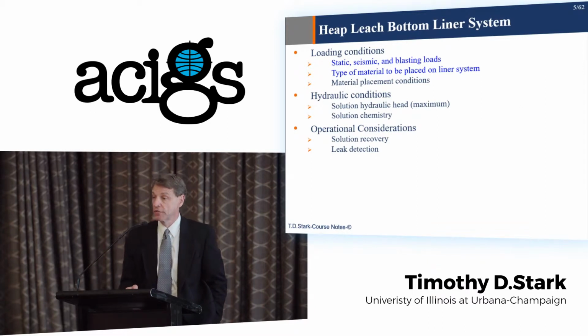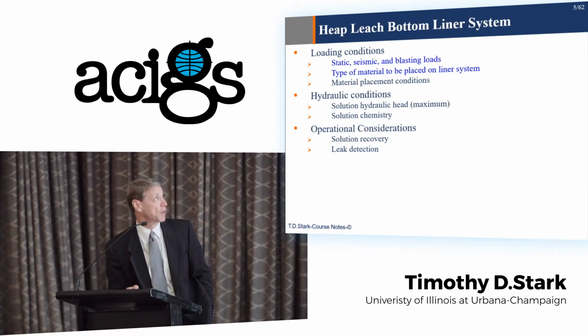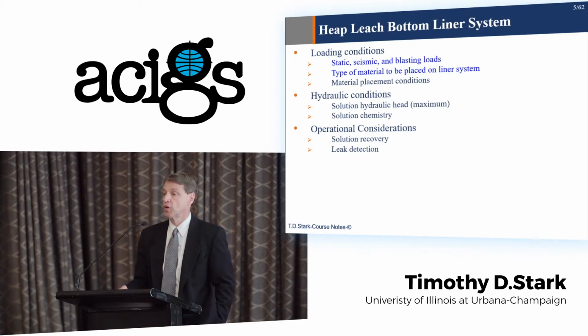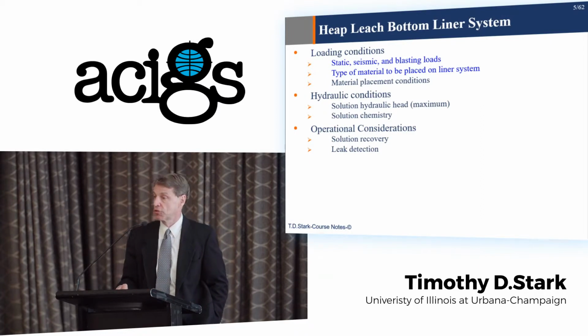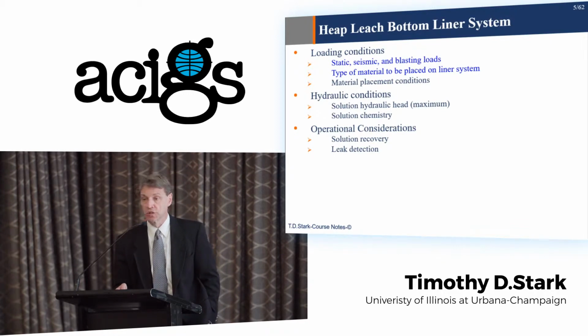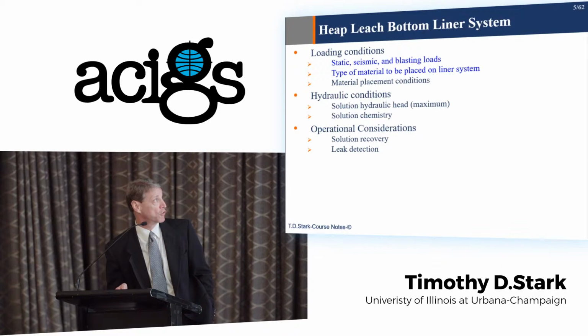Type of material to be placed on the liner system, not only the composition of it, but angularity of it, and so that'll help us decide about puncture resistance, how it's going to be placed, and then another key is the hydraulic conditions, what solutions are going to be used, because we have to make sure the geosynthetics are chemically compatible with the solutions that are going to be used for the operation.